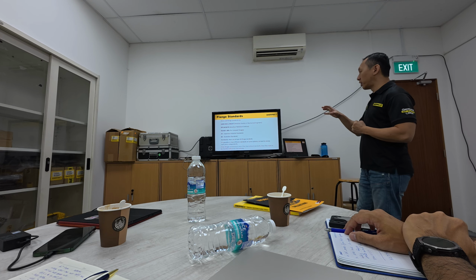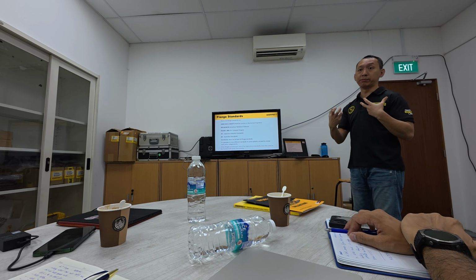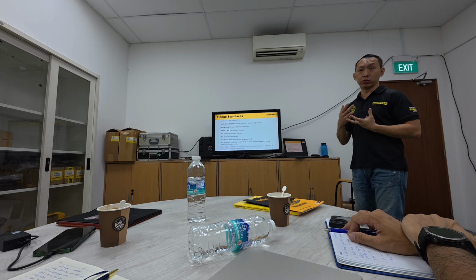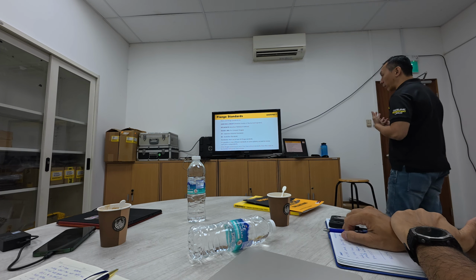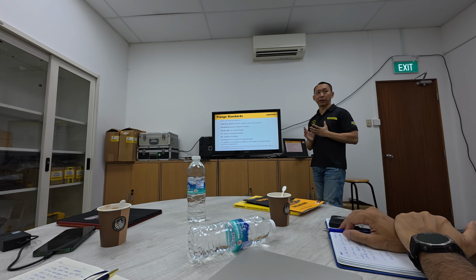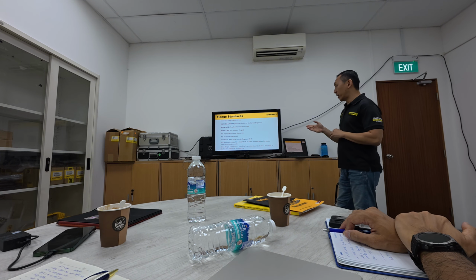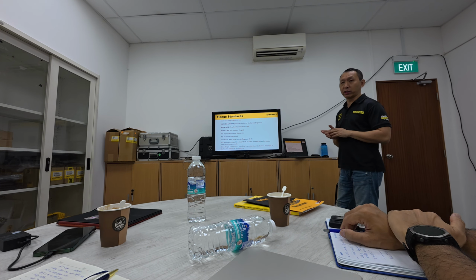It's possible to have different standards on the same system. It depends on where the customer buys from, or where the designer is from, usually. Yeah. So you might have different standards on the same system, so you review each joint independently. If the flange does not belong to any of the standards, then they need to be handled differently and carefully.